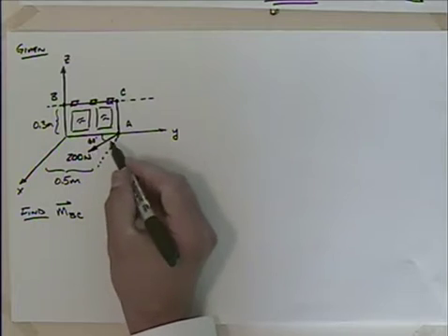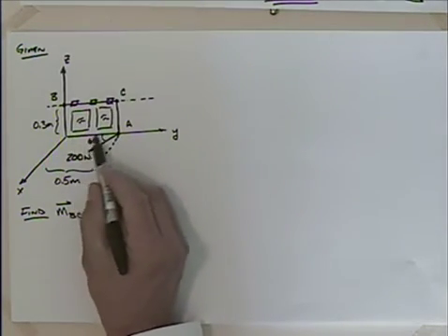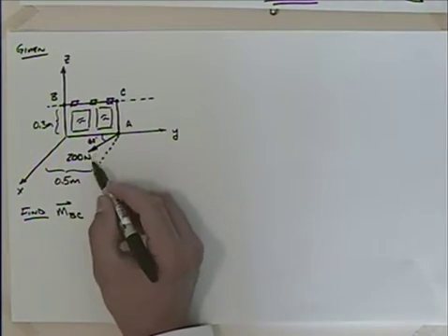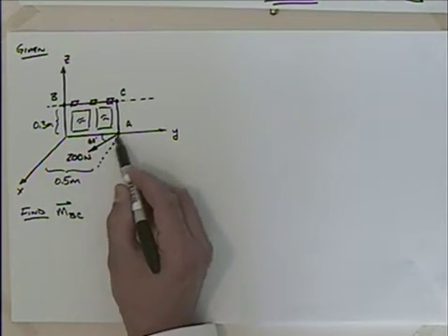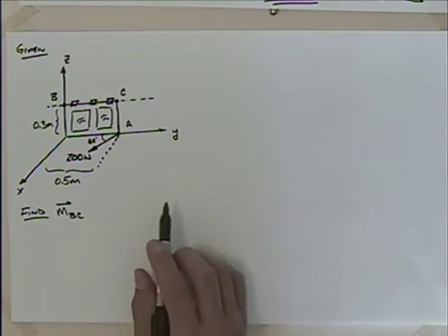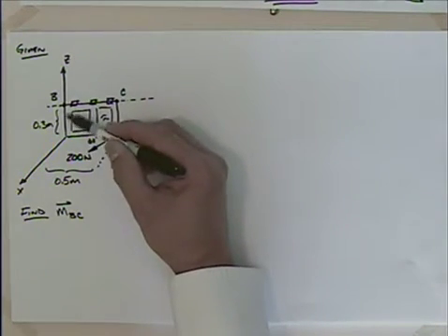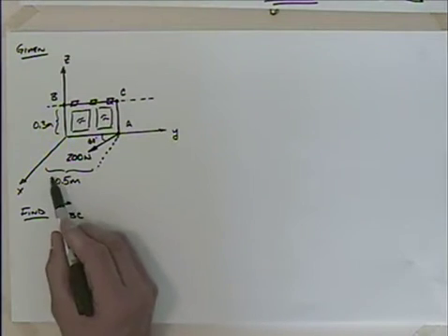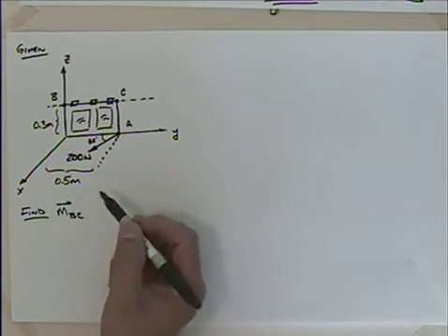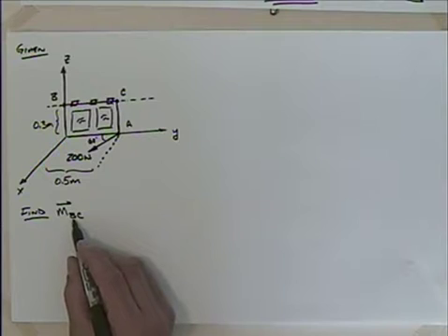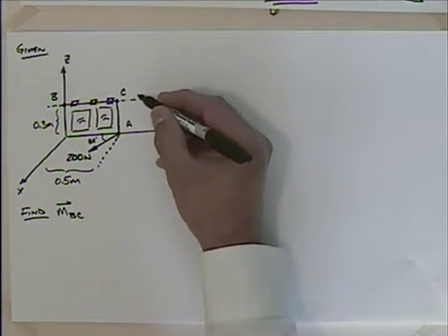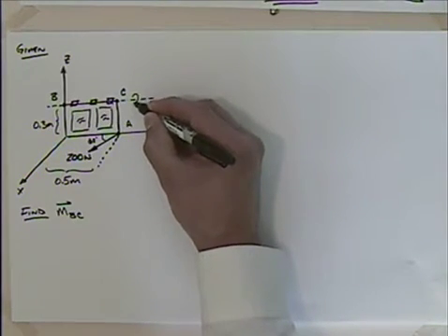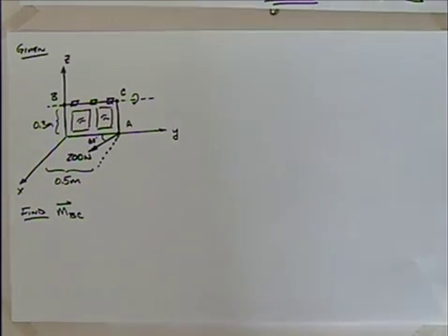And that 200 newtons is at an angle of 60 degrees with respect to this y-axis, and it is in the xy plane. The height of the window is 0.3 meters, and the width of it is 0.5 meters. And what we'd like to do is find the moment about BC, because the other pieces of the moment aren't going to go to opening it. The only one that helps open it is this moment that goes around there, right?